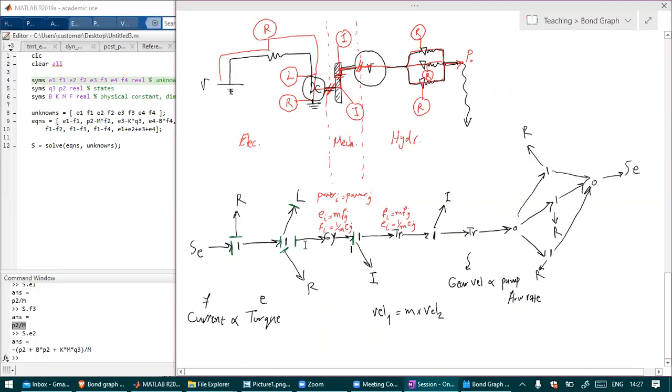So the left port, the flow is defined. F is defined. Yeah. So it's a gyroscope, so we use this equation, the effort on the other side is defined. And since the effort is defined, the causality sign should be on the far end. So that's how basically the causality of gyroscope looks like. The causality sign will be either both inside or both outside. Okay, that's it. Then for the one junction, we don't have the flow determined yet, but the I helps us.